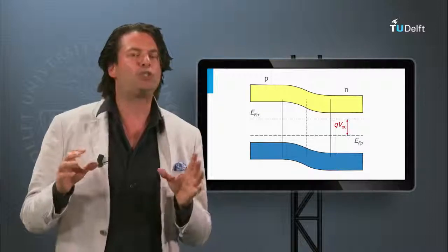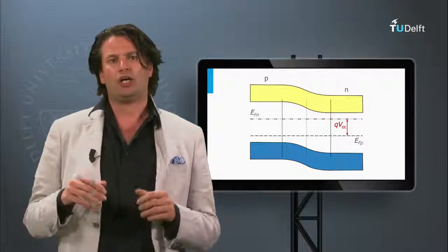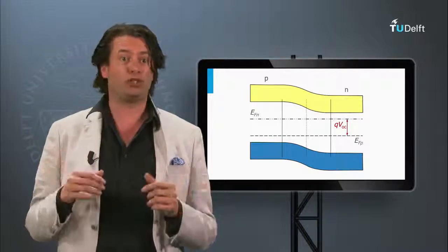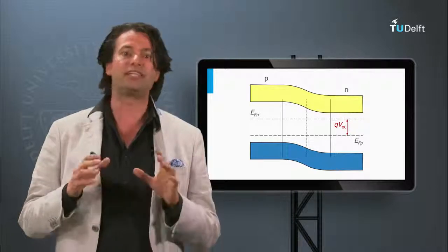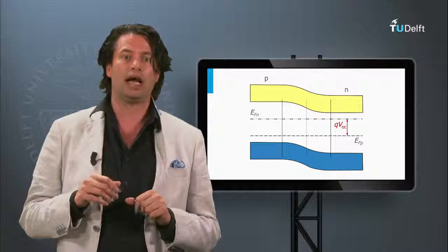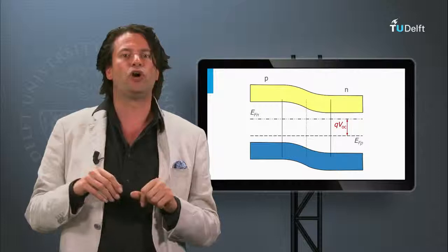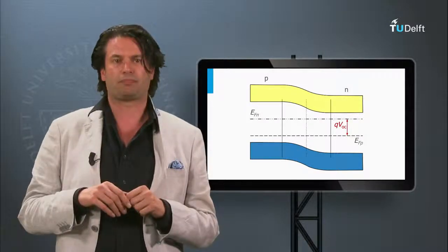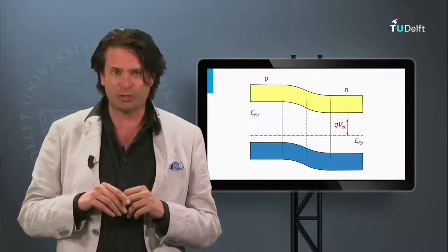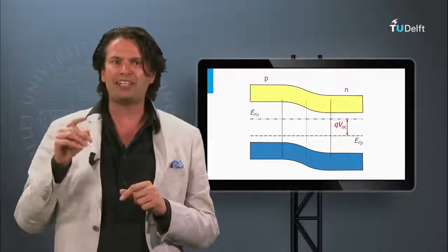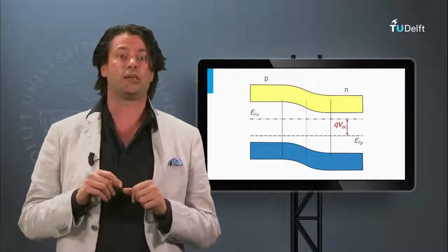Summarized, the open circuit voltage is limited by the dominant recombination mechanism. The dominance of radiative, Auger or Shockley-Read-Hall recombination depends on the type of semiconductor materials integrated into the solar cell and the illumination condition. In the coming weeks, I will give various examples of various PV technologies. In the next block, I will discuss the second design rule, spectral utilization. We answer the question of how much current density we can generate with a certain semiconductor material.